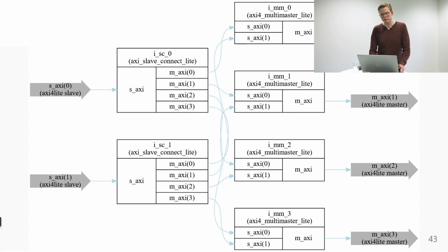And because we have all those objects in Merlin, we can not just generate HDL from it, for example, but we can also do different analysis. So we also have some tools to do some graphical analysis on the design, for example. So what you see now is actually a view of all the bus interface connections within this crossbar that was defined.